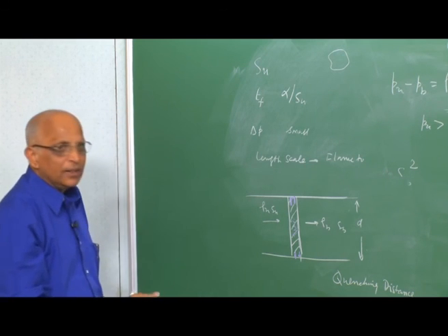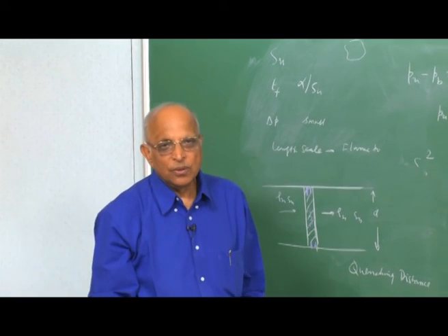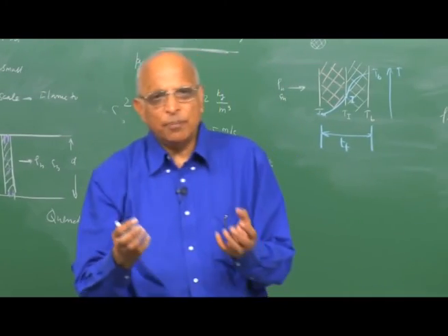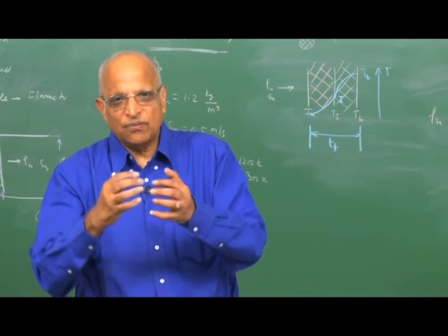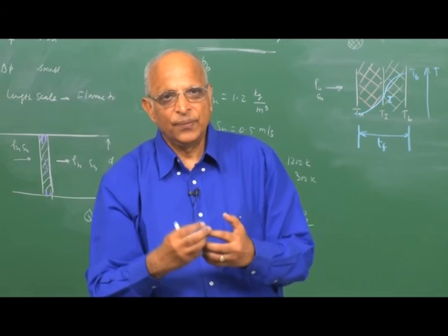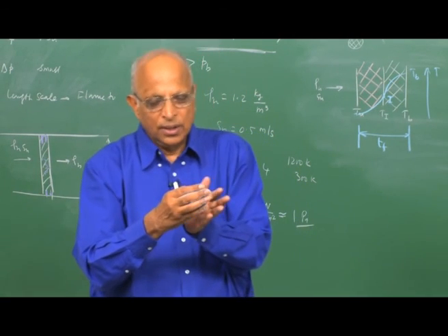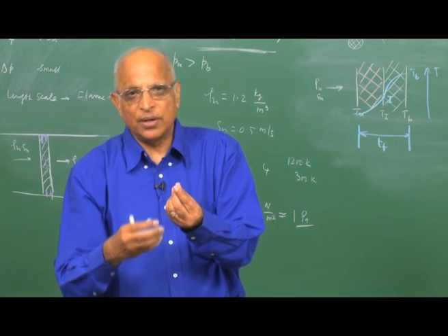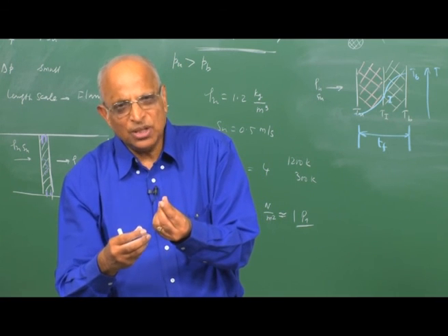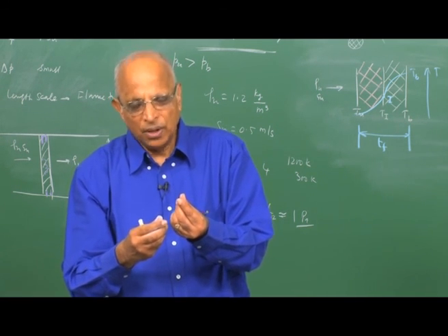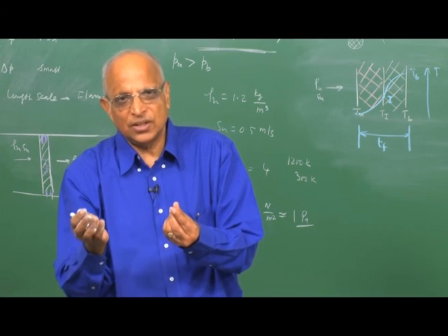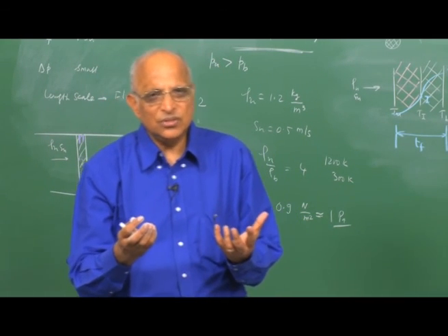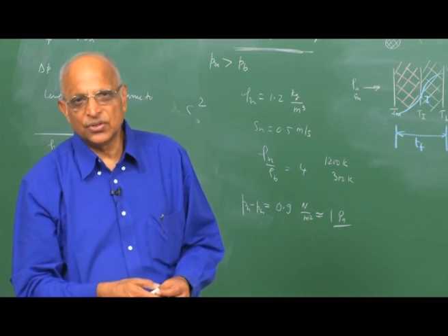Therefore, to just review what we have done today, we find that we have relaxed the assumption of, let us say, a lumped mass system. We looked at the ignition of a gas at a particular point, and therefore, from this point the flame or the combustion wave propagates ahead. We said, yes, I now know how to estimate the speed at which the combustion wave propagates. I know the thickness of the flame, I know that the pressure drop across the flame is extremely small, even though there is a drop across the flame from the unburned towards the burnt side. And now, we will do in the next class the quenching thickness, that is, the quenching distance, and thereafter model the ignition. Well, thank you.